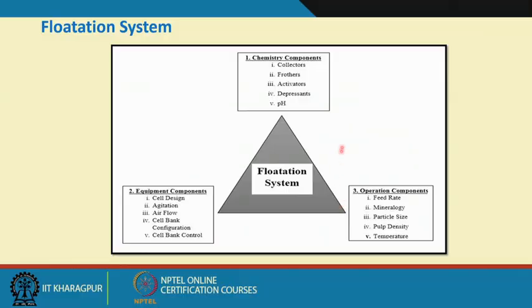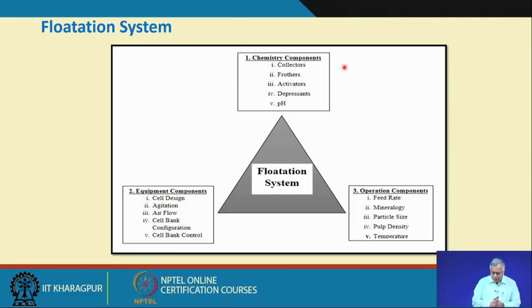Hello, welcome. So, we are discussing flotation. We have discussed the flotation system, which has three main components. One is the chemistry component, where we talk about the collectors, frothers, activators, depressants and pH. Then another part is the equipment component: what type of cell it is, how we will agitate, what will be the airflow, how many cells we require. All these things are dealt with under this topic,